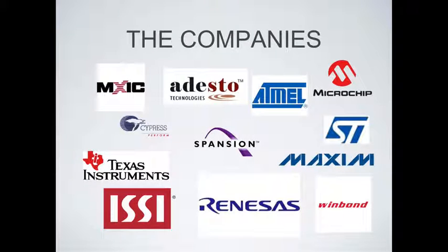Okay, so we're talking about the companies that make these chips. What are the most common companies you might find? I've found quite a bit of Micronics, which is the MX stuff. I've seen a couple of Microchip. I've also seen ST, Atmel, Cypress. Usually when you see Cypress, you're not going to see the word Cypress. You're only going to see that little tree on the chip somewhere.